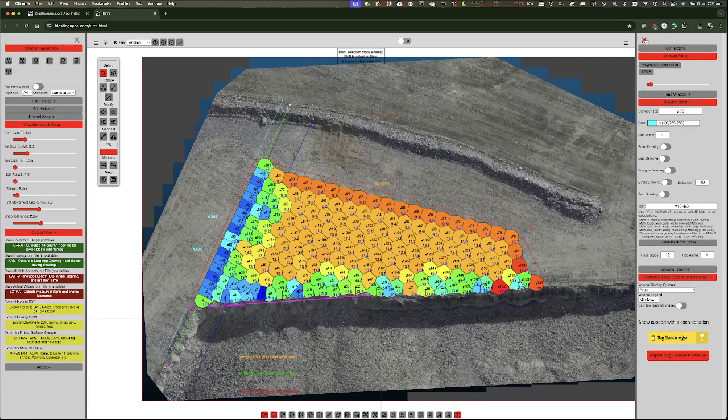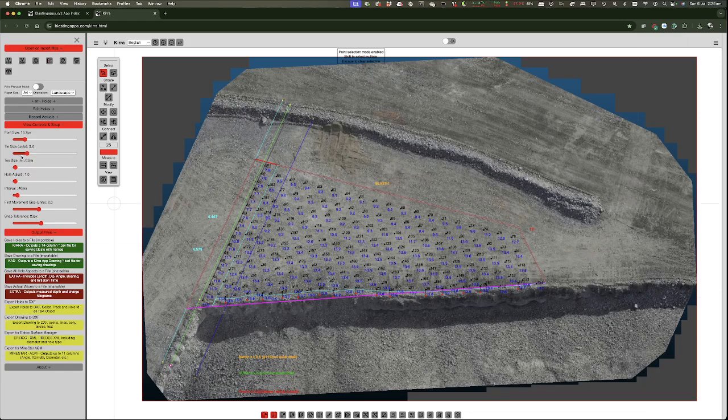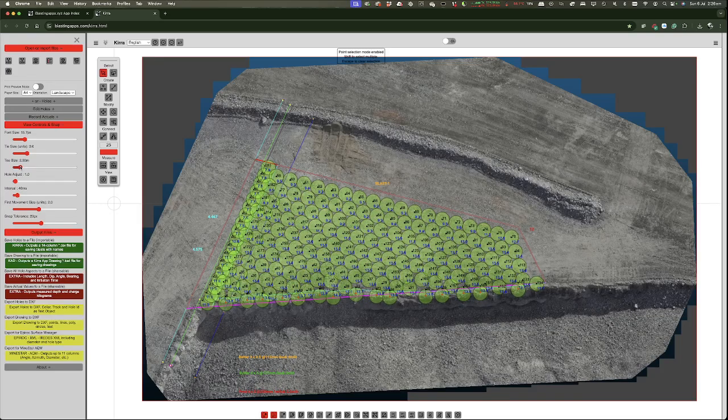If you're placing blast holes on the bench and you want to check their relationship with other blast holes, you can turn on the toe size and dial that out, and where you see overlaps or gaps, you can see that you've likely got high energy or low energy. There's a gap in here that we can address by adding a second hole in there, or we can move that hole back, or these holes into the space, so that it's all good. If you moved a hole, you'd have to reassign the surface. So we've done all that.